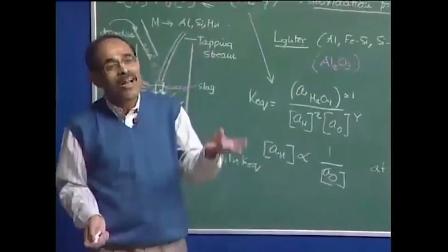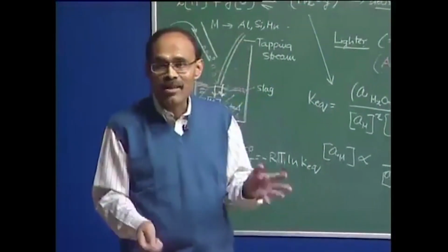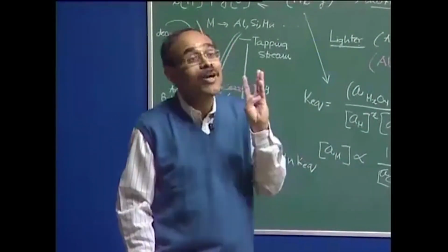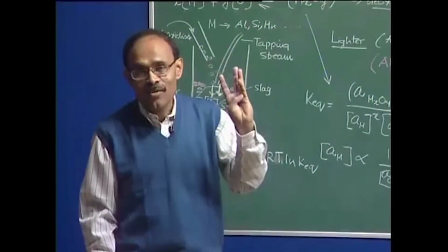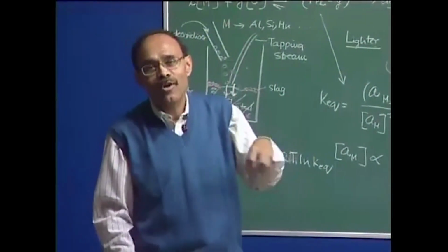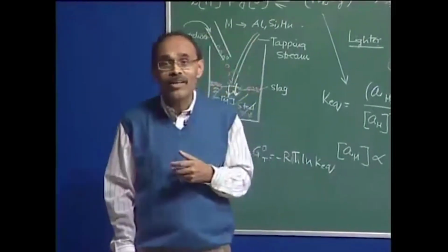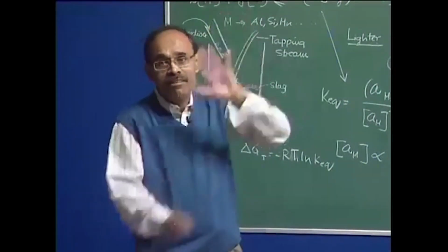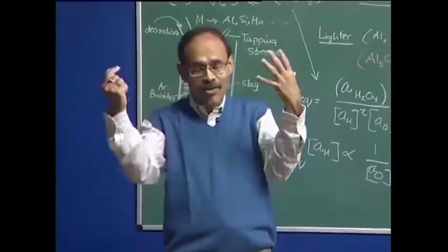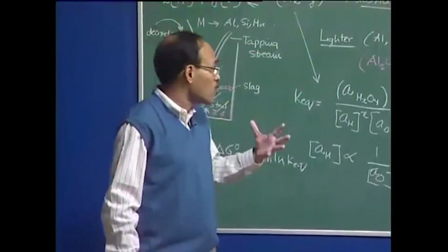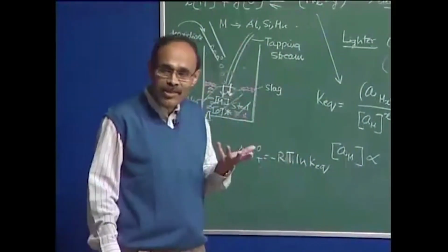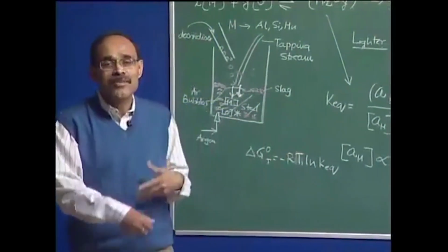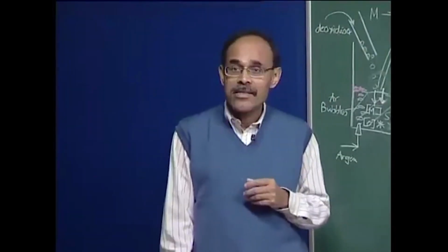We have solid deoxidation product, liquid deoxidation product, gaseous deoxidation product. Solid is not wanted, as far as possible, but aluminum, which is such a powerful deoxidizer, which gives low residual and can bring down oxygen to a very low level with only a little contamination, unfortunately forms a solid deoxidation product. We want the final steel to be devoid of these deoxidation products, which we will later call inclusions, and contamination of steel with deoxidation product is referred to as dirty steel. An associated subject is cleanliness control, and so on.